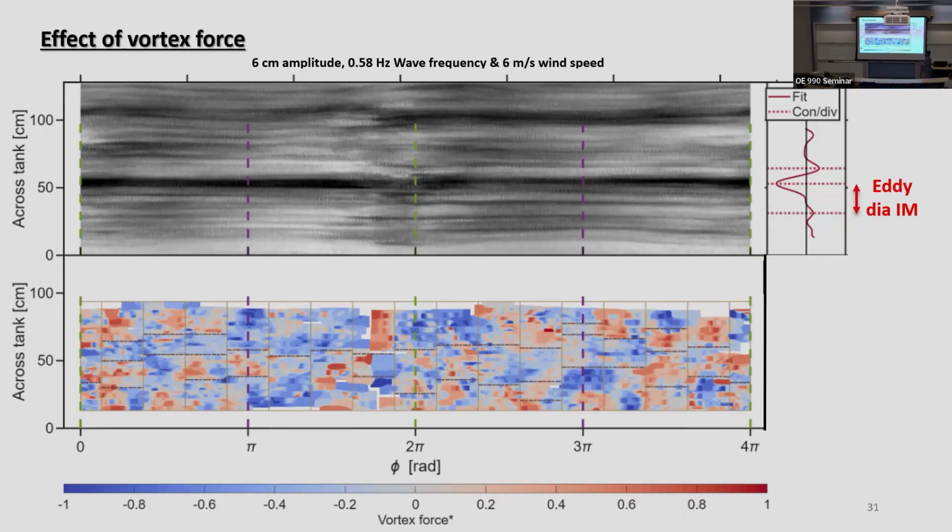Now this is the vortex force contour map right here, which was calculated using Us cross omega and then stacked up in the phasogram and then averaged, right? The vortex force is a second order term. It accumulates over time, and these consistent regions of vortex force crossover, the change of sign from negative to positive, were shown in the previous slide.